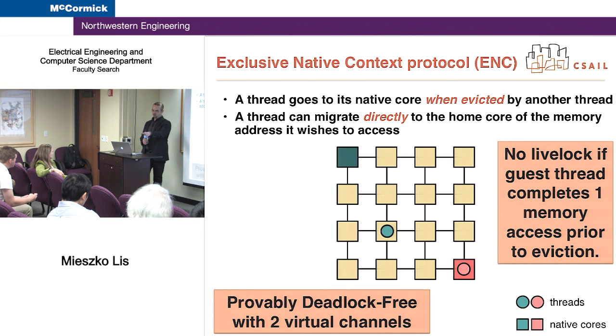Yeah. So in this chip that I passed around, there's no power down or power gating. There's clock gating. Conceptually, you can do this, obviously, right? But in some sense, we have this problem in architecture where we have all this area, but we can't power it all at the same time. This is the dark silicon business, and well, what are you going to do with all this dark silicon anyway, right? So as long as you can keep it off when you don't need to use it, I think it's reasonable to use extra hardware.